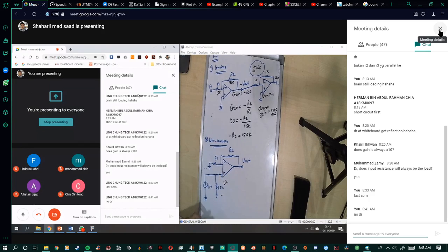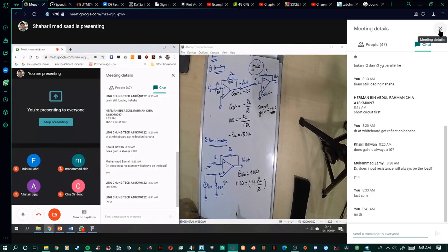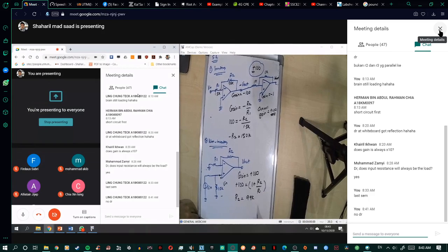Now you want to get the gain of plus 100. Gain of plus 100 means 1 plus R2 divided by R1. So let's say we choose R2 as 99k and R1 as 1k.